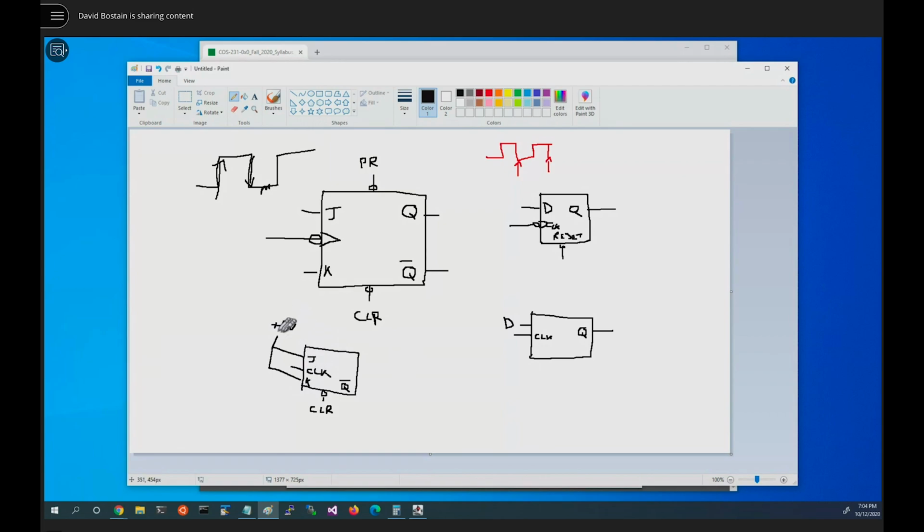It's a JK flip-flop wired up so that it will toggle the not Q output. There is no Q, there's only an inverted Q. And as he pointed out to us correctly, an asynchronous clear is available, meaning we can hold clear, and while we're holding it, this will not toggle. It'll just keep this at a 1. Why would it keep this signal at a 1? Anybody want to take a shot at that?